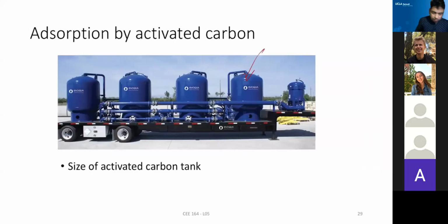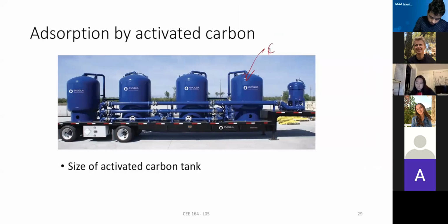This carbon adsorption is a pretty popular technology, and the material you use is activated carbon. It is most popular because it's cheap compared to many other treatment technologies. The side effect of this technology is that you have to deal with the spent activated carbon, which means you have to dump it in another landfill. That's the risk. Also, once activated carbon is exhausted, it's very difficult to reuse unless you regenerate the capacity. So learn all that.